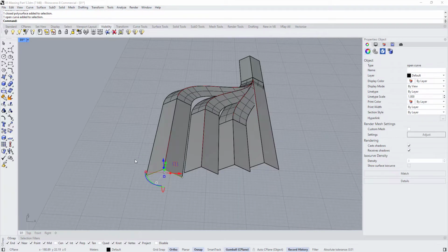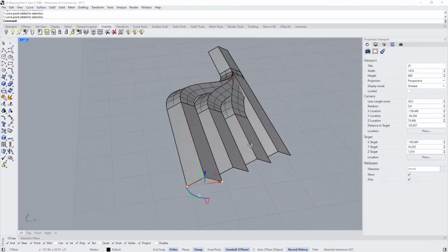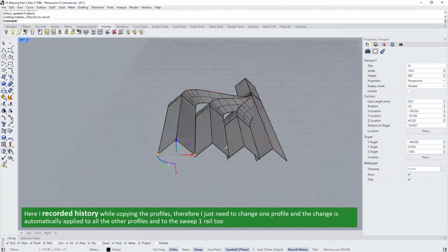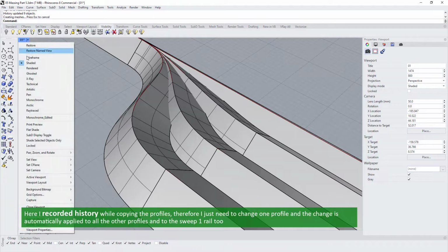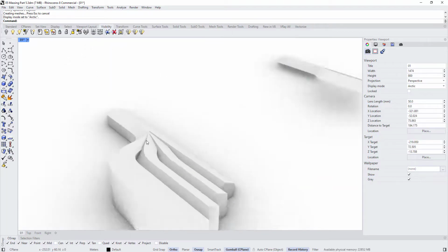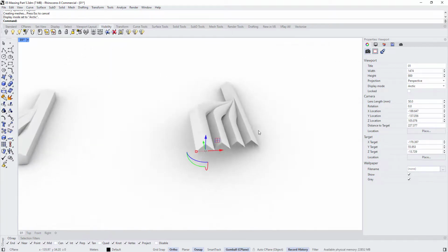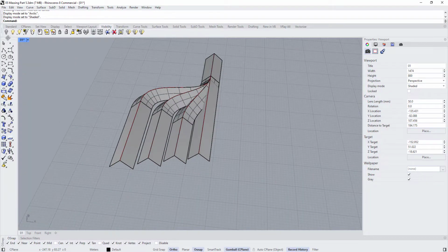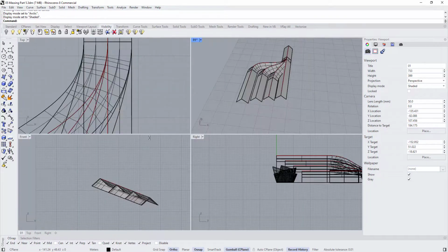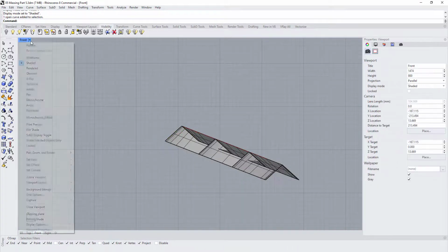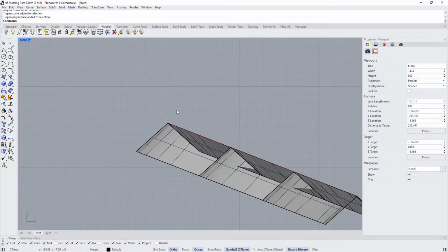So for example here, if we want to keep these steps, you might need to increase the slope more so it becomes more emphasized, not just a very small connection like this. And now I will show you how to eliminate it completely. To eliminate it, we can come to the front view. Let's stay in the shaded mode.